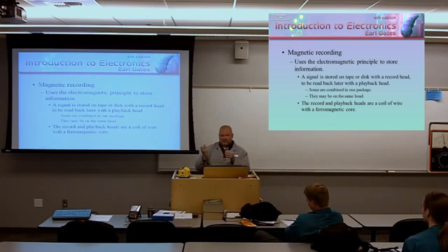The microphone, which also is a magnetic device, picks up the vibration of the air molecules moving back and forth and transforms it into a small electrical signal that gets amplified and connected to the record head. The record head fluctuates its magnetic field, putting those iron filings on the tape into a unique pattern.